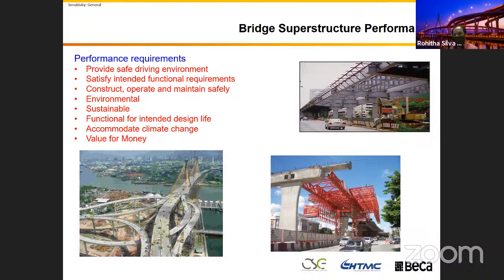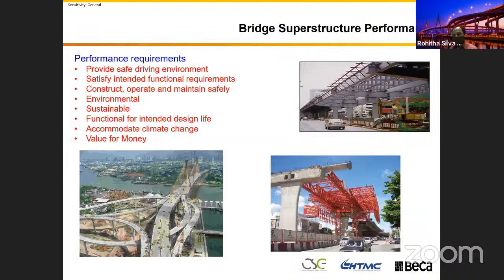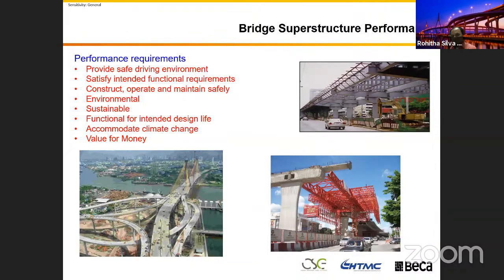That's true, especially temperature and also the stress reversals. Pavement on a bridge is not on the ground where we know the behaviors, but it's flexible, because hogging and sagging moments are there. So the pavement layers on top have to be designed accordingly. We have so many issues. You will see the cracks, especially on bridges with link slabs. You will see that a couple of slides later. I have a stress calculation actually.